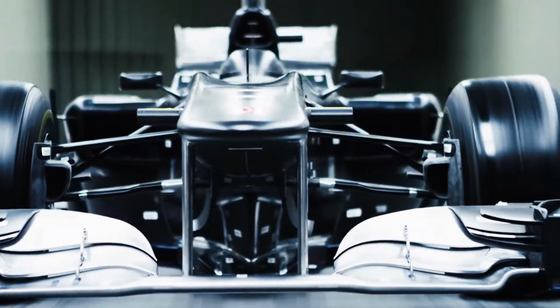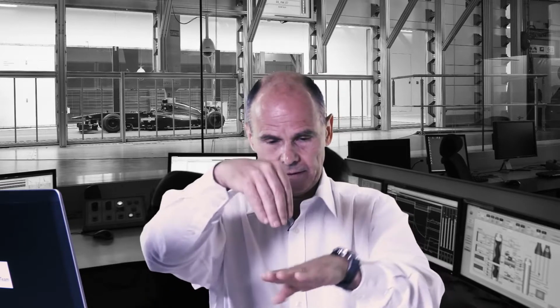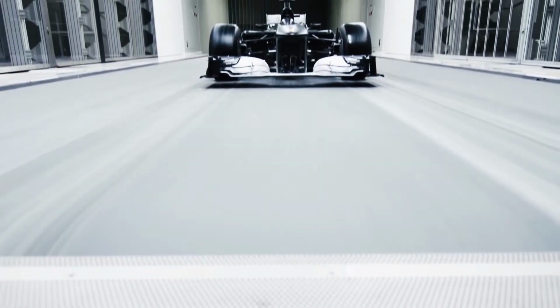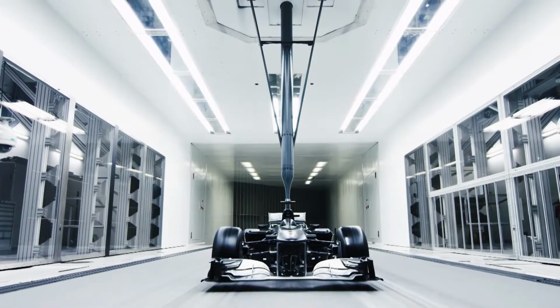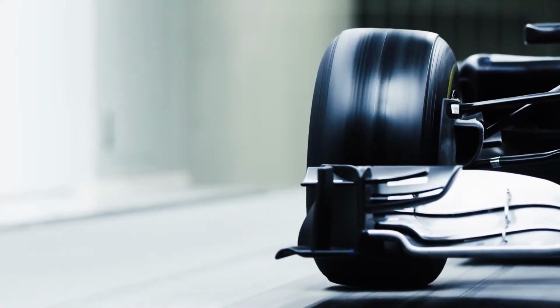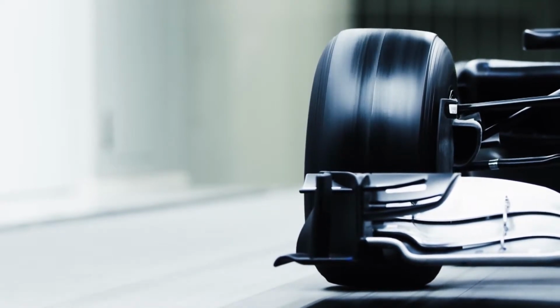We have load cells in the axles of the wheels, and we also measure the forces underneath the wheel contact patches. Now that's extraordinarily difficult to do, because between the tyre and the load measurement we have a thick, fast-moving belt system. But despite that, experimentation and calibration has taught us that we can measure the load that the tyre uses to push down onto the belt. We can measure that by having a specifically, carefully designed high pressure air bearing load cell underneath the spot where the tyre exists.